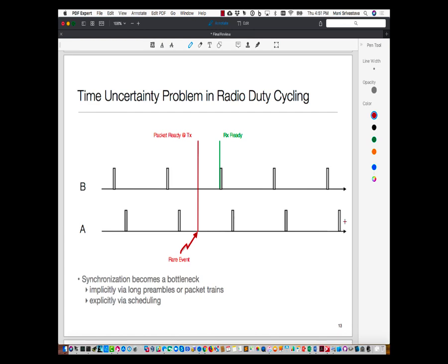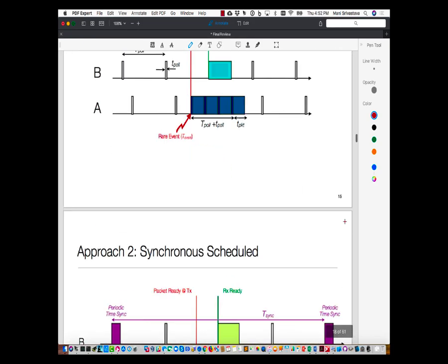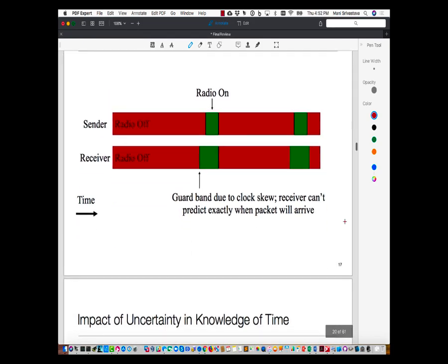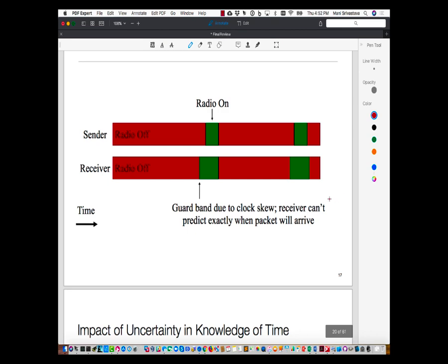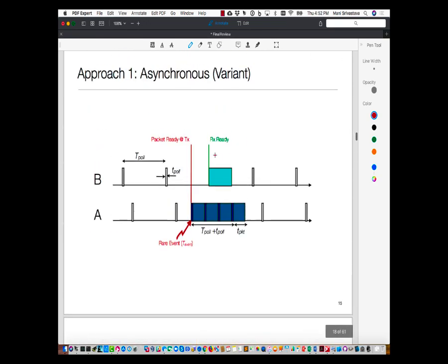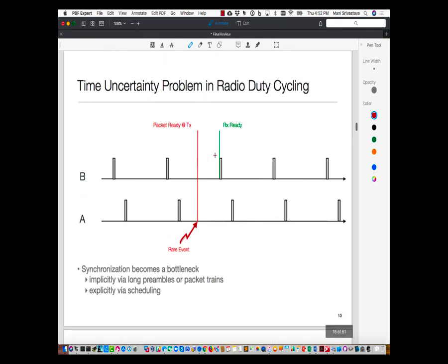So usually when you do need to know something about the hardware, you say this is the type of clock being used, so much drift will happen, and we had talked about the notion of guard band. In fact, I think I included that slide out here. So you budget some excessive time during your wake up to take into account possible clock drifts.